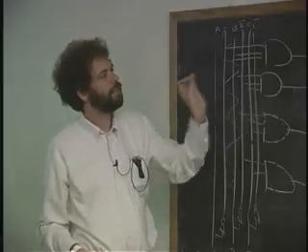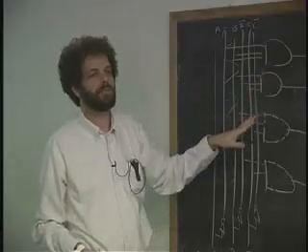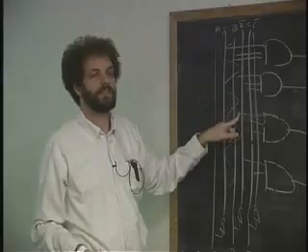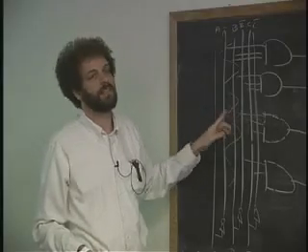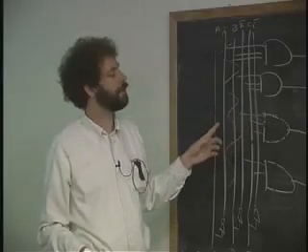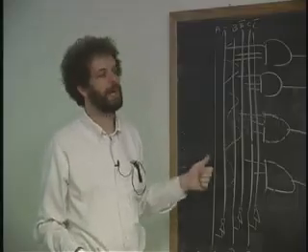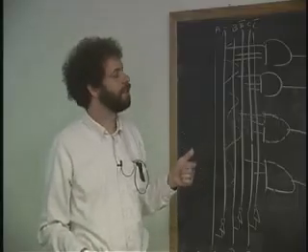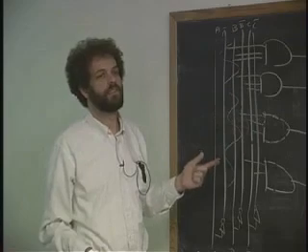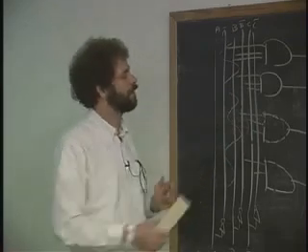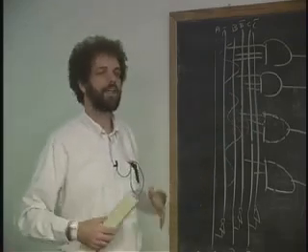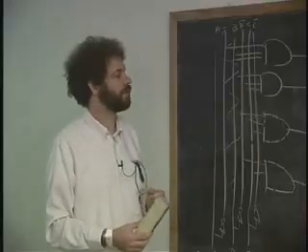And if there's 2 to the 31 AND gates with a lot of them on the same wires, there's a lot of charge that needs to go in and out. And what does that mean? A, the amount of power you need to do that is very large, and B, it's really slow. Because if you supply the charge at a fixed rate, the amount of time it takes to charge them all up is a long time.